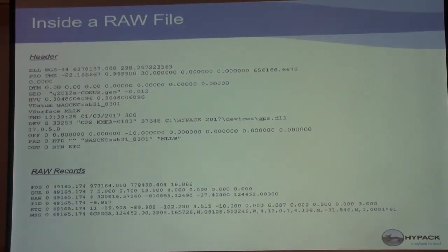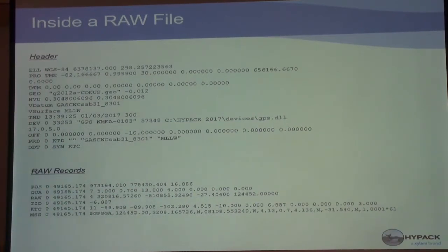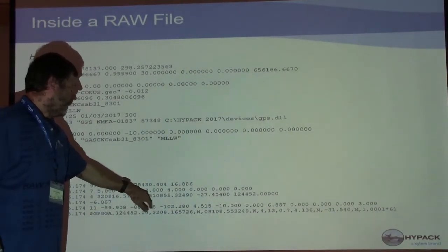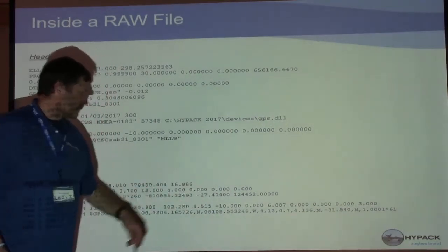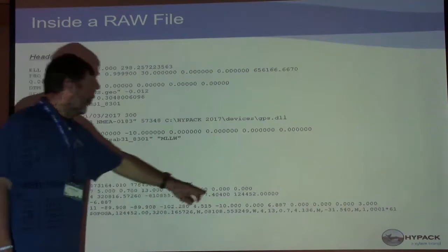The raw record is really important. This is the device number again, the same time tag. The time tag goes throughout all these different values here. The number of values following, then we have our latitude and longitude. It's the NMEA standard, which is decimal minutes times 100. So 32 degrees north, 81 degrees west here. Our ellipsoid height coming from our GPS, and then our UTC time.